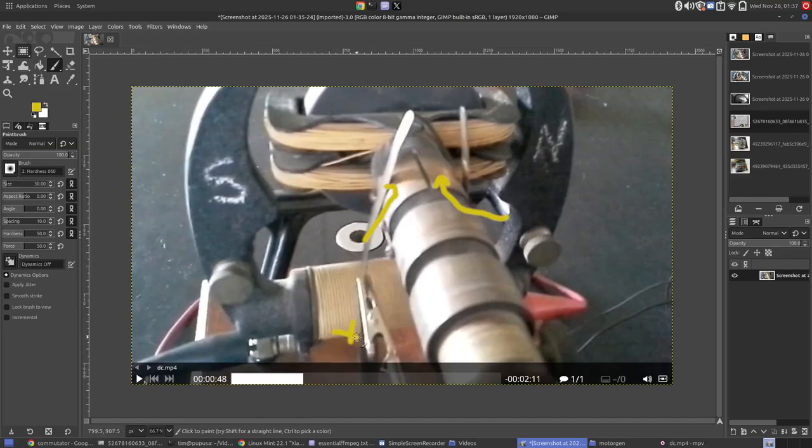And bottom line is, because there's these brushes, one of which is hooked up to the positive side of the galvanometer, and the other is hooked up to the negative side of the galvanometer, we don't end up seeing a reversing alternating current, because at the point when the current would want to switch direction, the commutator has rotated and it connects to the other brush.